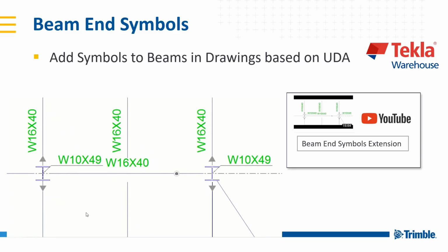So this is the Beam End Symbols tool, also an extension from the warehouse, as I mentioned. And what this allows you to do is, based on user-defined attributes, or UDAs, on my model objects, I'm able to populate symbols on the ends of beams in drawings automatically. So this could be a moment connection, this could be a slip critical connection.